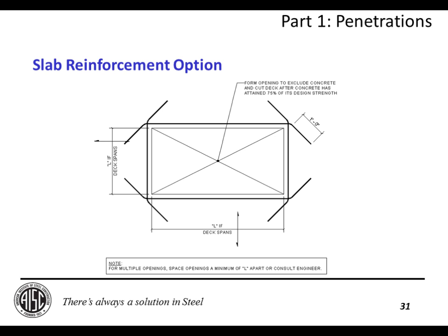There's been some tests run where the anchorage extended all the way to the very top of the concrete, so it had zero cover, and it really had no effect on the strength of the member. So the only thing that you really need to be careful of in that is maintaining things like fire rating. So as far as the strength issue, it's okay to violate that limit in an in-place condition, and that's why the specification is pretty clearly worded that it is a detailed 1.5 inches. So indeed, if it doesn't, or a 1/2 inch, if it doesn't come out, then it's okay up to a point. Obviously, if they're sticking out of the slab, then you've got other issues. Okay, great. And we have one last question.